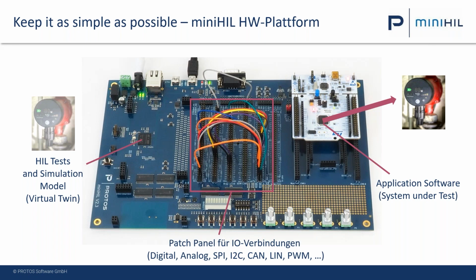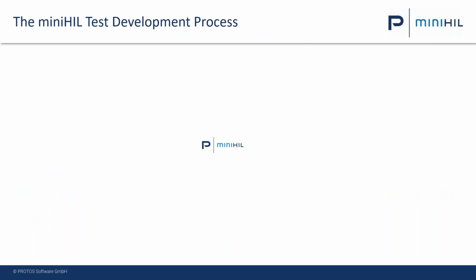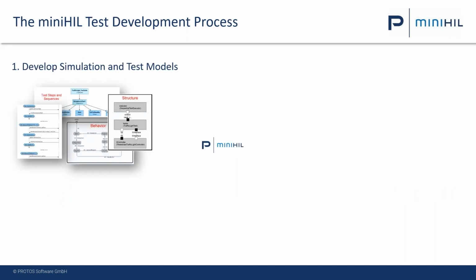Okay, so now we have a hardware platform where we actually can connect the I/Os of a microcontroller to a test system. Now we need to model the environment simulation and we need to model the test cases. For that, we have a model-based development environment.